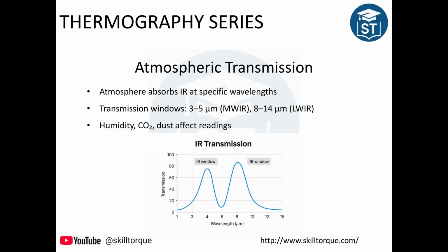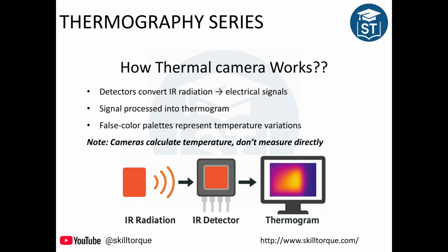So depending on that. Okay, now we will move to another section: how an IR camera can see heat. Whenever you are planning to take an IR image of an object, the first thing in your IR camera is the lens. You will focus on that object with the help of this lens, and the lens will only allow a certain wavelength of IR to pass through it. What is that wavelength? We have already discussed before. The wavelength lies somewhere between 3 to 14 or 15 microns.